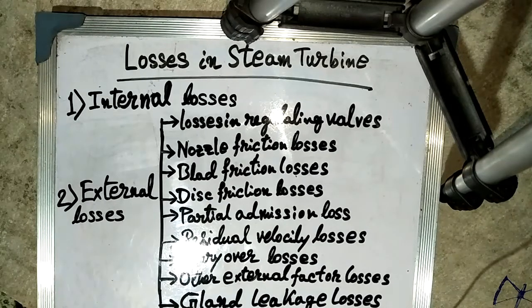However, due to the large number of stages, the total surface area exposed to flow is more, which increases the friction losses. Thus, the nozzle losses depend on its size, the surface roughness, its length, the roundness of entrance, the divergence angle, the space between the nozzles, moisture and trailing edges.